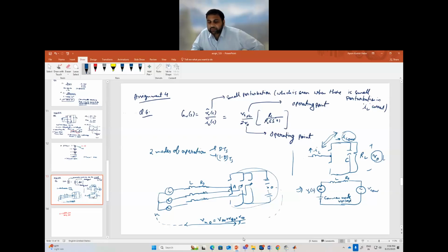Now, since we have defined the fundamental component of the circuit, we are writing omega L, where omega is nothing but 2 pi fs. That means we have defined the single phase equivalent circuit in fundamental harmonic terms. So all the voltages other than the fundamental harmonic components will be zero if we just apply the superposition theorem. That is why we have a circuit which goes like this.